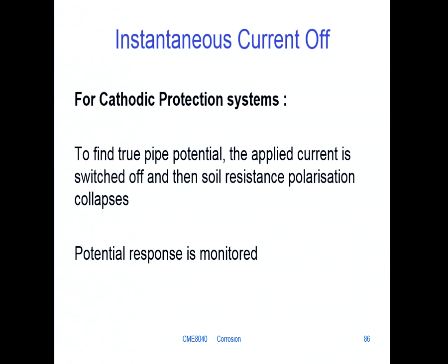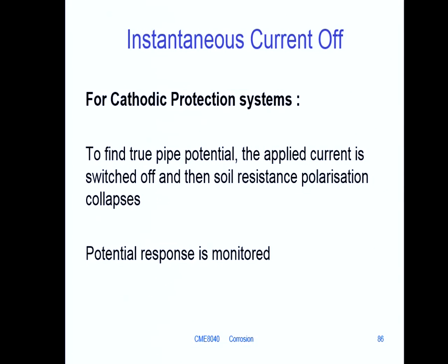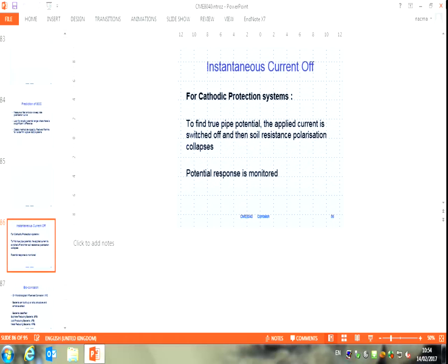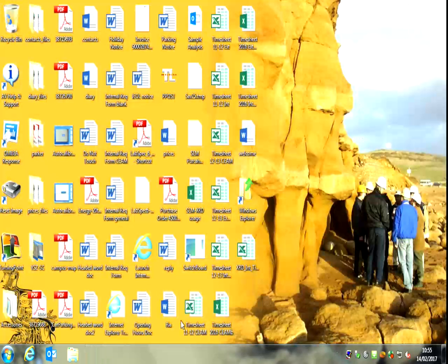The initial condition, we have a passive film on all the surface, including the crack tip. Well, you might not even have a crack tip. It might be flat. Well, there has to be some sort of stress concentration. Maybe it's a change in geometry. But wherever that stress concentration is, that can cause the film to crack, and then corrosion will occur, and then it'll passivate again. So you've got to have a combination between tensile stress and passivation, film formation.